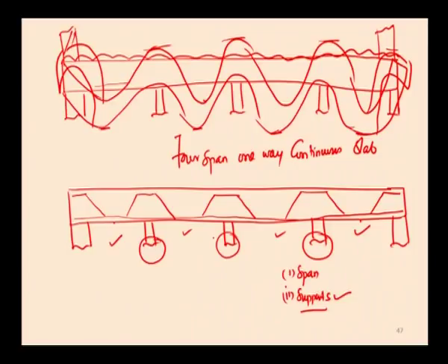If you design the reinforcement separately for all 4 bending moments, there will be a chance of congestion or overlapping of reinforcement one with another, and we can't provide concrete over the reinforcement. To avoid this, we normally design the reinforcement against the maximum moment. Which moment is normally maximum among the 4 bending moments? The moment at the support next to the end support is always maximum, since the moment coefficients are like that.